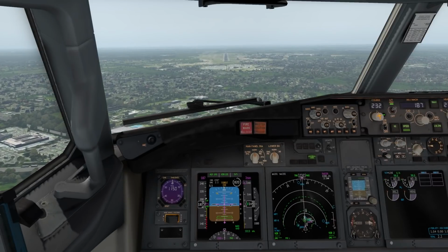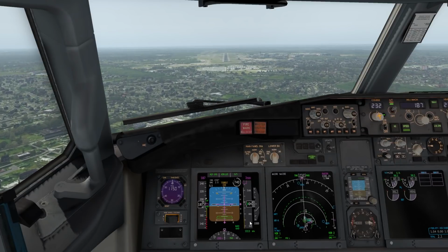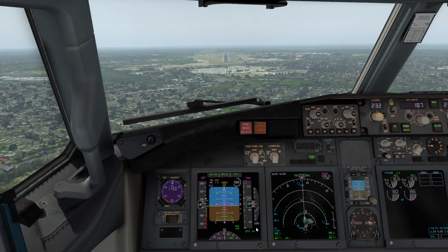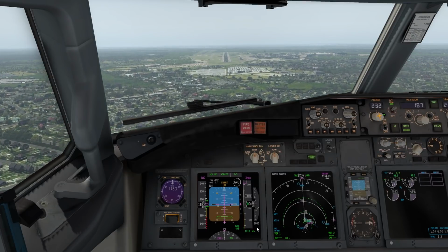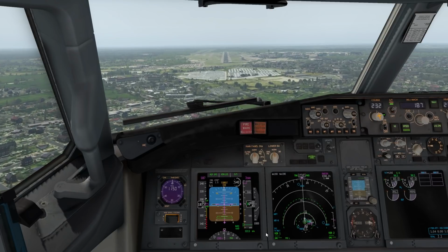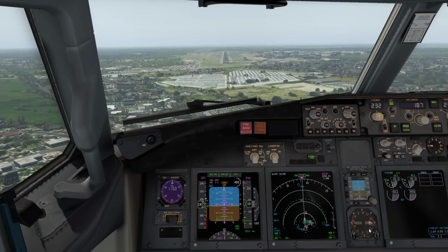So below 1,000 feet AGL, we're ready to take control very shortly. Again, everything's stable. We've already mentioned how the rate of descent might be around or in excess of 1,000 feet per minute. So long as it's something sensible, not excessive, we can continue at the landing gate. So there we are, fully stabilised. Discuss the rate of descent, approaching minimums as well.